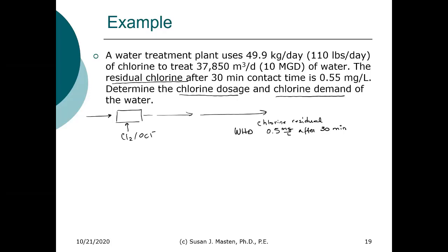The New Zealand regulations say that at the point of delivery, actually it's a recommendation, there should be an available free chlorine of 0.2 to 1.0 milligrams per liter. Remember, in Christchurch, until very recently, they weren't even required to disinfect.